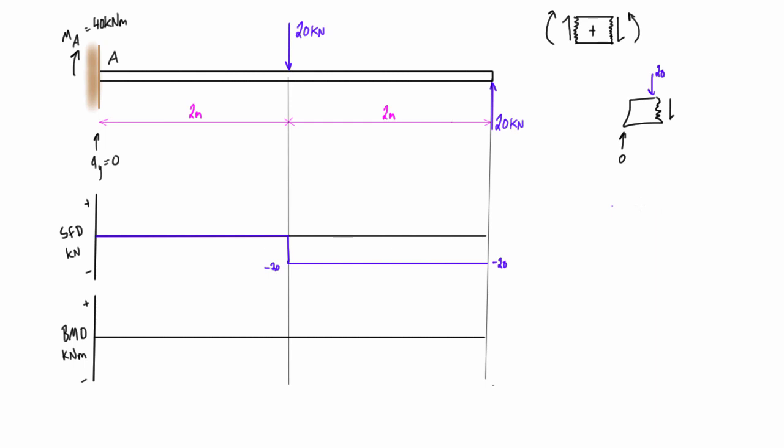Now we do want to check that we've ended in the right place. If we draw the Freebody diagram of the right hand side of the beam, taking a virtual cut just to the left, we know we have this point load of 20 pressing up, and then the shear force has to be 20 pressing down. Pressing down to the left of a virtual cut is opposite the positive sign convention, so that's a negative sign, magnitude 20, and that's exactly what we've got: negative 20 kilonewtons of shear at the end of the beam, so we've done this correctly.